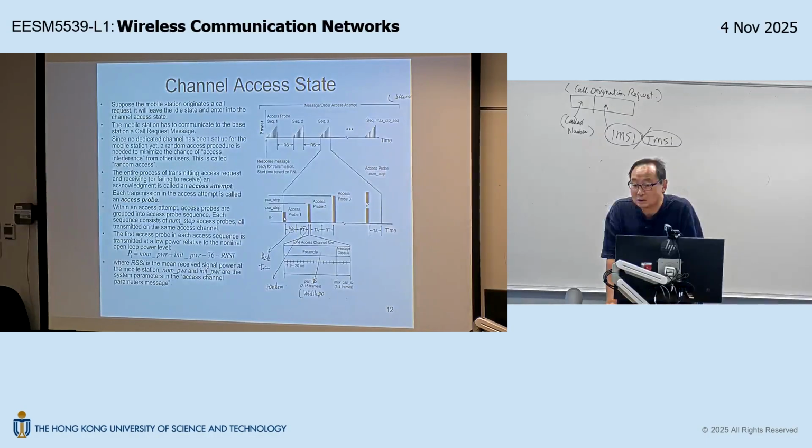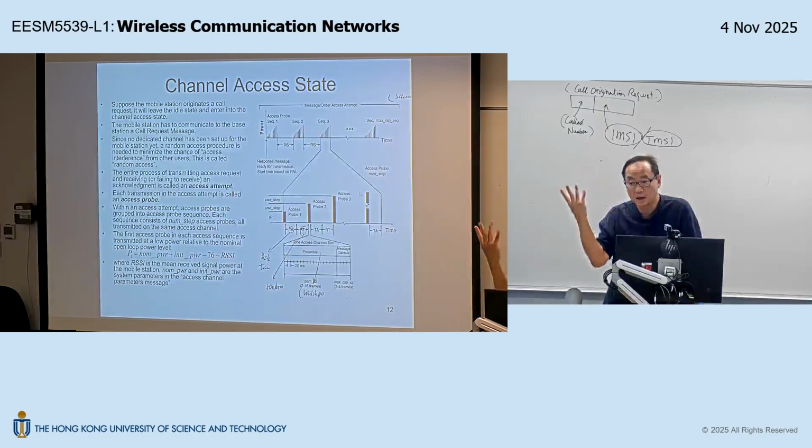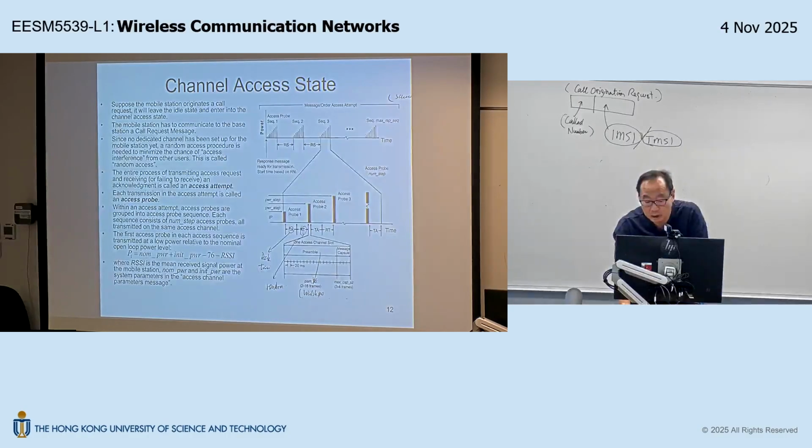Is that okay? So in response to this problem, what is the solution? So that's why in the next transmission, I gradually increase my power, right? So in my next retransmission, I don't retransmit with the same power. I retransmit with a slightly higher power. This is to overcome this potential issue of insufficient transmission power. Is that okay? So this is like somebody at the back, initially, you whisper your request to me. I can't hear it. I cannot give you an ACK. So next time after you timeout, acknowledgement timeout, you start to retransmit your request, but with a louder voice, right? Then keep on increasing your voice. Okay? So that explains this power ramp up.